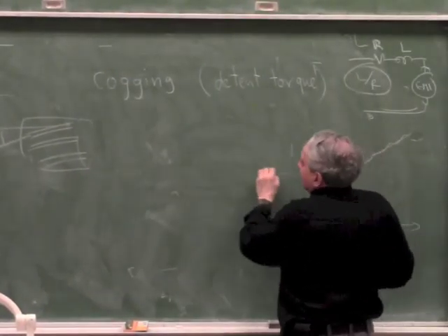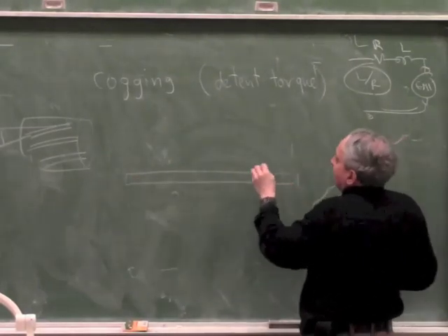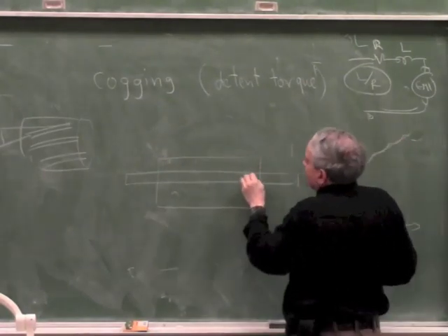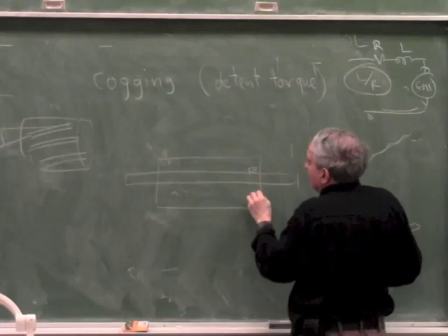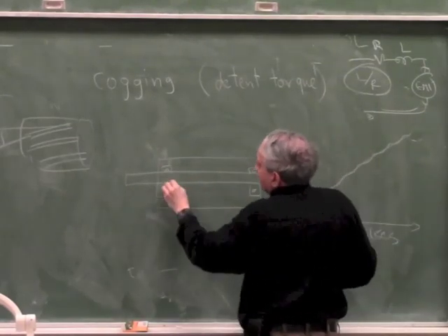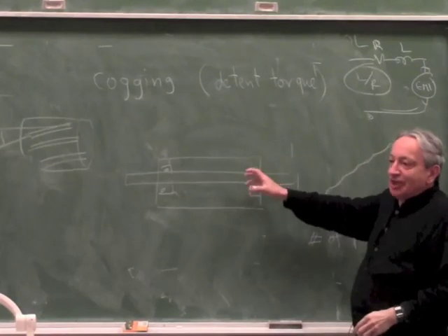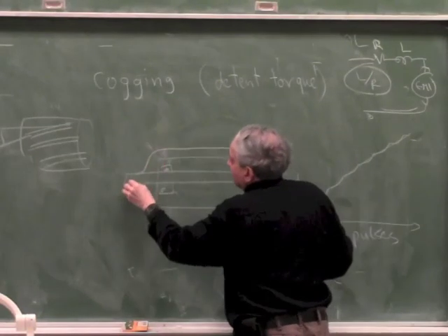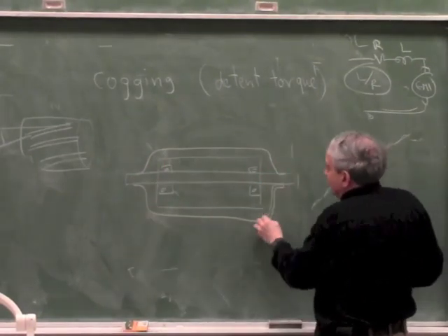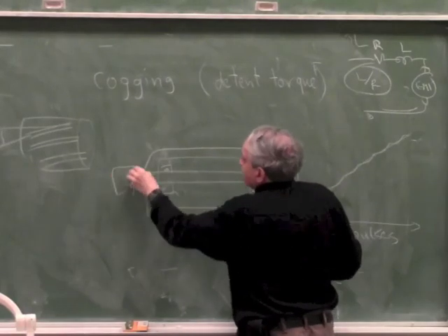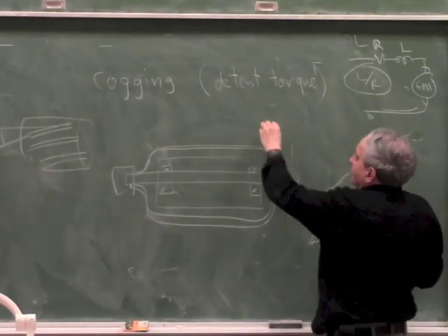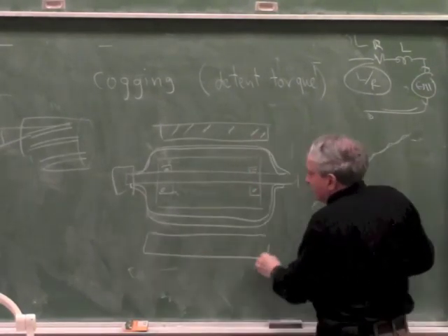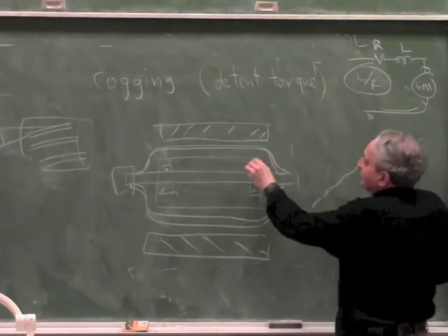And this is to have a shaft, to have the magnet inside the shaft on bearings. So the magnet is sitting on ball bearings, either the magnet or a piece of steel, it doesn't matter. So the magnet can freely rotate on the shaft. Okay? And now to have the winding around it as a shell connected to the shaft. So this is a commutator and this is a winding, and the winding is a shell, and then to have the ring of steel which closes the magnetic path. So this is just a ring of steel to close the magnetic flux.